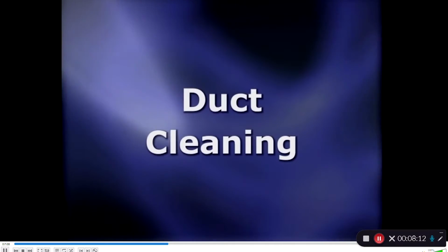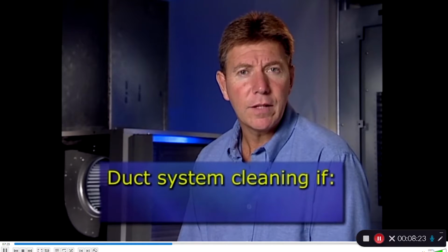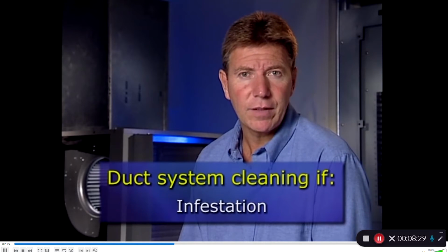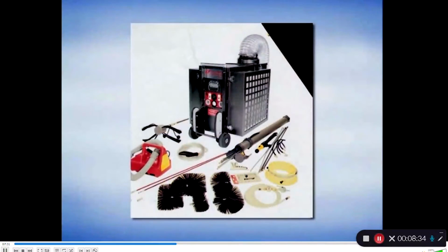Air ducts are often a contributing factor to the amount of pollutants that are present in homes and buildings. Having a duct system cleaned should be considered if there is substantial mold growth, indications of infestation, or if there is excessive dust in the duct or on the supply registers. Duct cleaning generally refers not only to the cleaning of the interior of the ductwork, grills, diffusers, and heat exchangers, but the cleaning of condensate drain pans, fan motors and housings, humidification equipment, and the casing of the air handler as well.